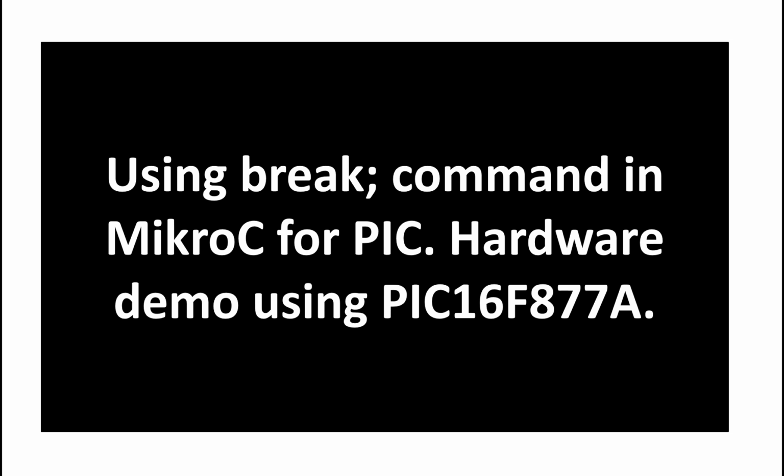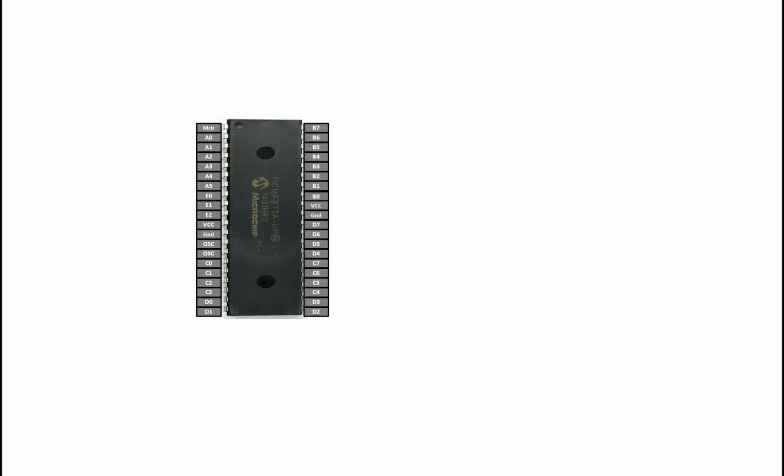So guys, this over here is our PIC16F877A microcontroller having 40 pins. It's a DIP version. Before we move forward, let me first show you the hardware I'm going to use. I will just use a push button and 4 LEDs. The 4 LEDs will be constantly blinking in a forever loop, but as soon as I press the button it will initiate the break statement, causing the loop to end. So that's what the break statement does. It makes sure that your loop ends. It will jump you out of a loop.